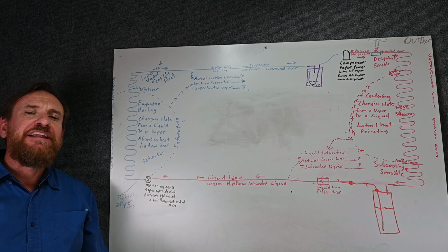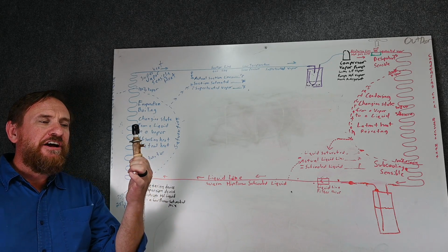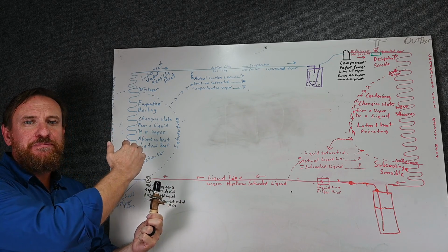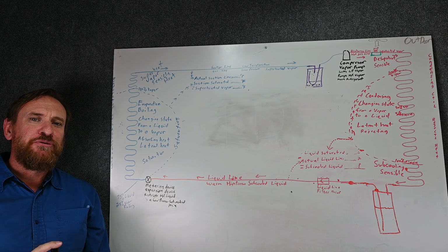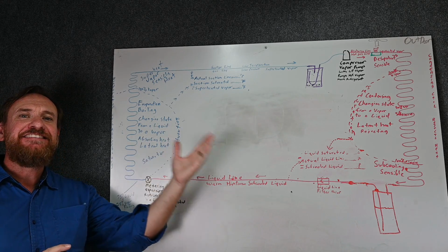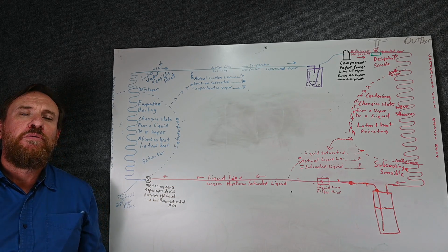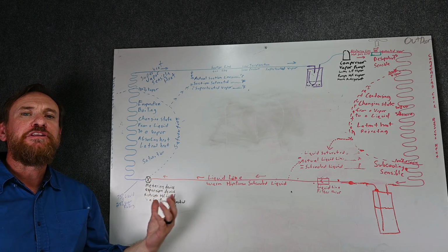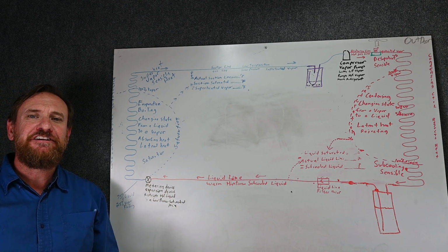So I want to put up some flags of caution for you. We know that the automatic expansion valve is the only metering device that maintains a suction pressure. We know that at laboratory conditions, that's the only way you're going to have set, non-changing pressures. We also know that the MeasureQuick app is one of the few ways that you're going to be able to see what those different pressures are going to be at different conditions.